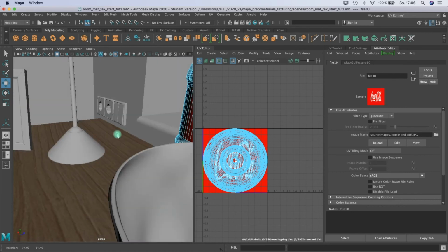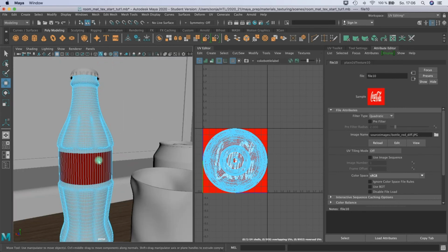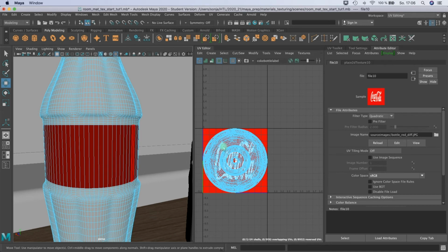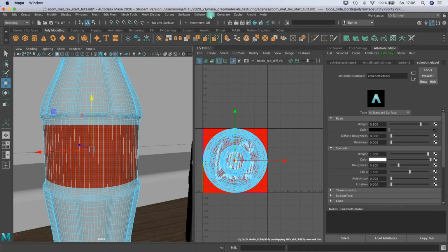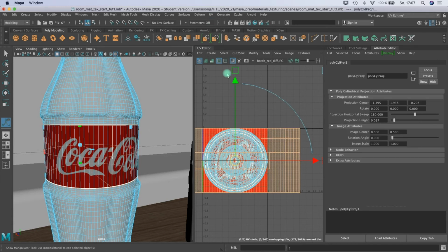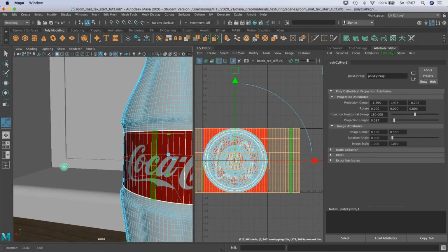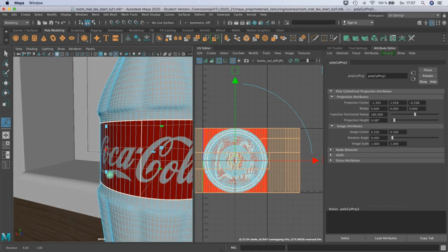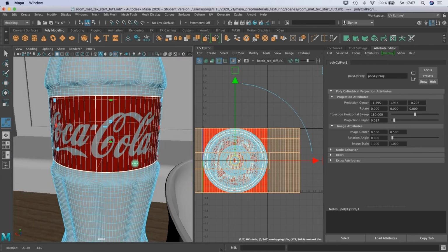Here we go. And of course I destroyed the UVs here also, and you don't see anything. So what I do is I select the faces again, and now we try a different type. We try the cylindrical mapping. Of course, this is obvious: when we have a cylindrical object, then cylindrical mapping can work cool. And yes, it is perfect as it is assigned here.